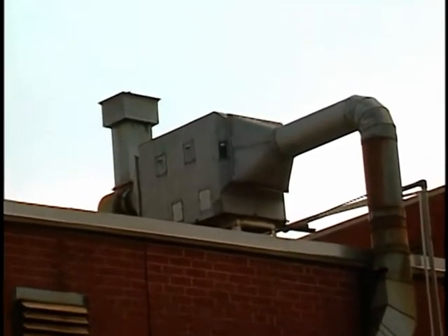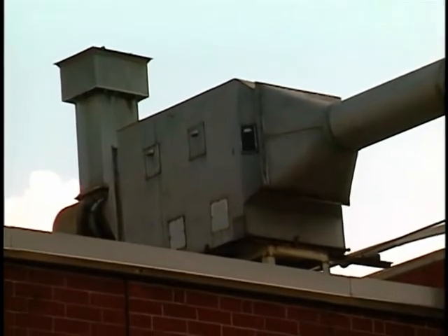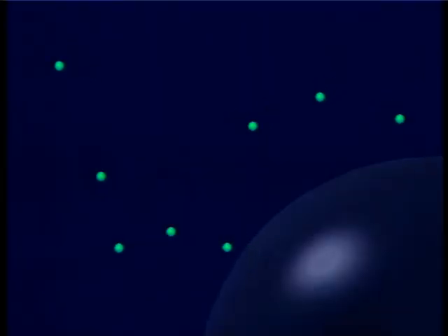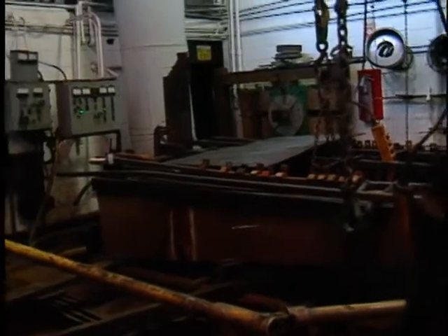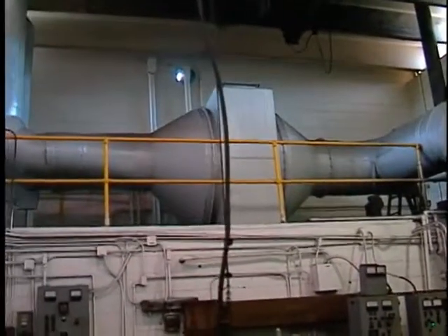There are other parameters associated with the liquid that should be checked. High liquid temperature can reduce absorption efficiency for units in which the dissolved contaminant does not react with the solution. High liquid temperatures are not a significant problem for reactive type systems, since collection is not limited by liquid solubility.